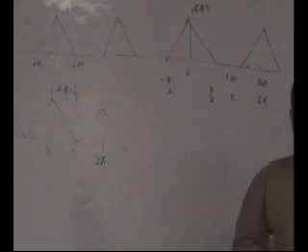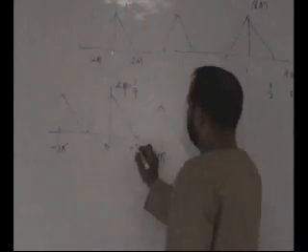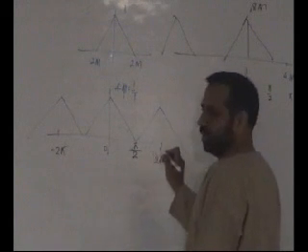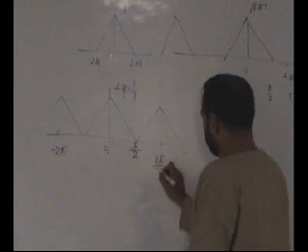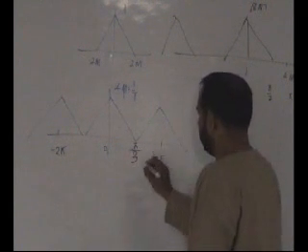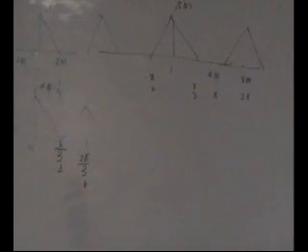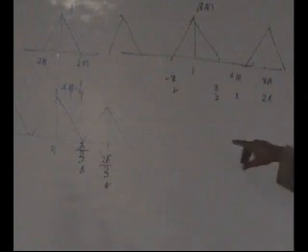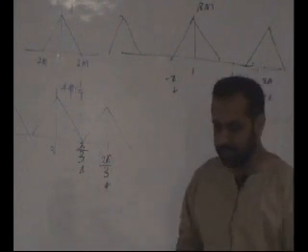Okay, this is what you do in interpolation: the digital spectrum, the pi here, should be divided by 2 or 3 or 4. If you divide the whole axis by 2, this 2 pi will also be divided by 2. If you divide by 3, this will be divided by 3. If you divide by 4, the whole spectrum will be divided by 4. So you want to somehow apply a digital transformation which can change this spectrum like this. It is done in 2 steps by just inserting zeros.